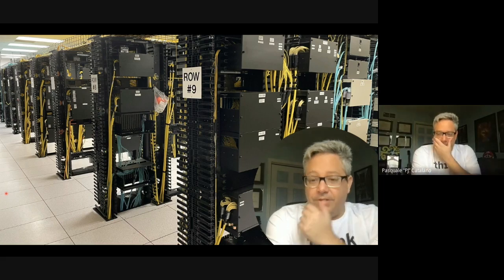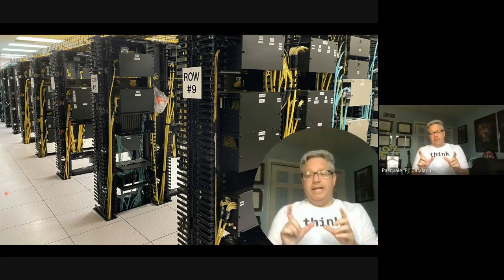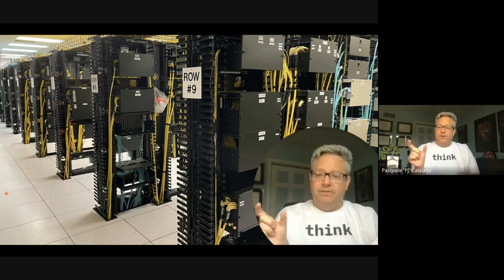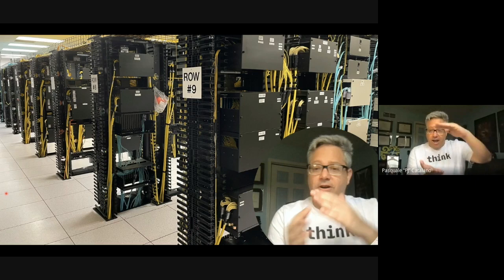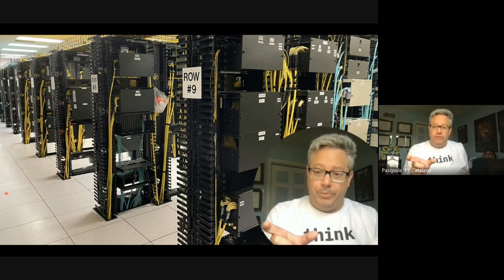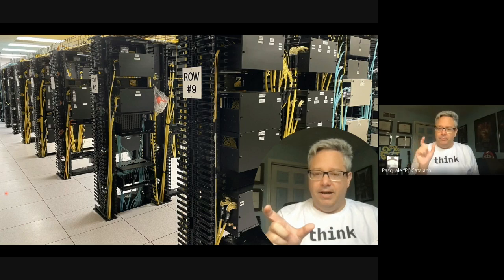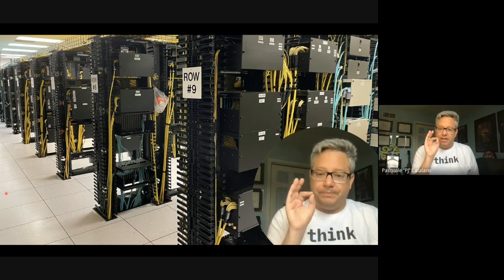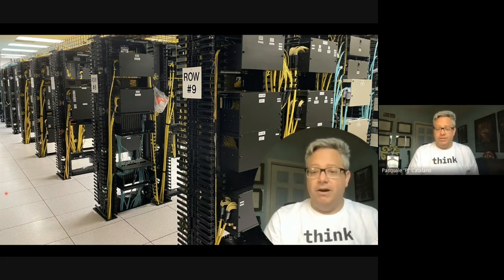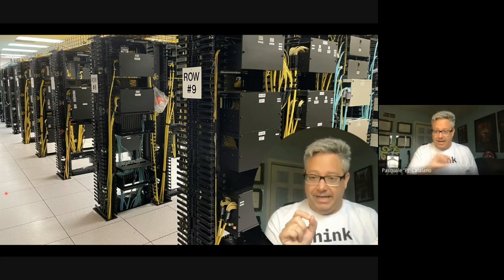Great question. So 10 kilometers is the rating on the optic, the fiber optic we use. I don't have a good picture of an I/O card coming up, but in our I/O cards, we have multiple ports. Each of those ports has what's called an SFP, small form factor pluggable optic. Those we get from a third party, but the rating on those for the long wave, those yellow cables, is generally 10 kilometers out of the box. That means that optic can go natively 10 kilometers of fiber.